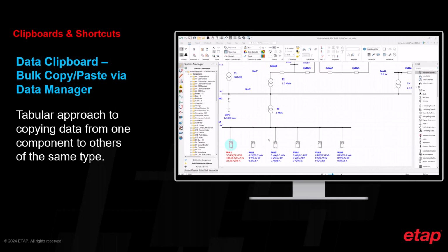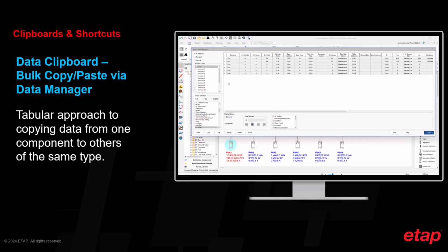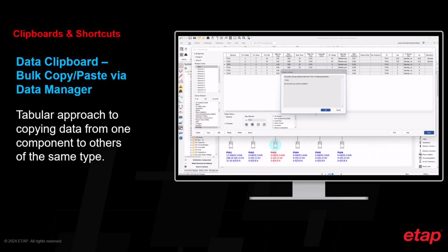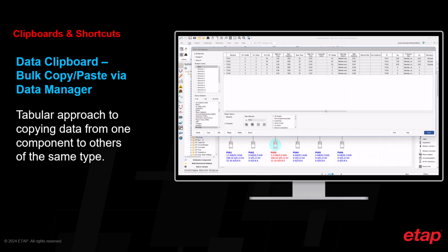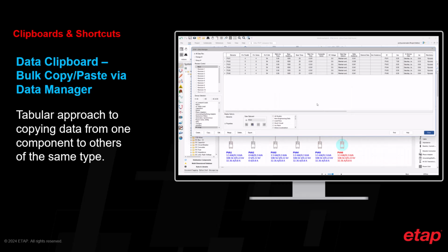Data Manager provides a comprehensive view of the properties of all elements and revisions in a project. While viewing a single revision in element type, you can leverage the data clipboard to copy a single component's properties to others of the same type directly in the Data Manager table. Here we've selected PVArray1 and copied its data to the data clipboard. We then select PVArray3 and paste the same data to apply all of the properties of PVA1 to PVA3. This can be repeated as necessary, again, per individual device type.